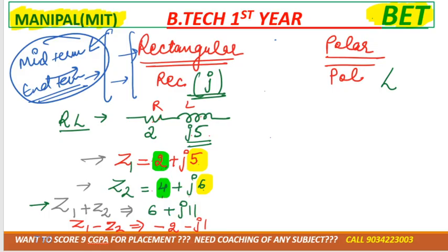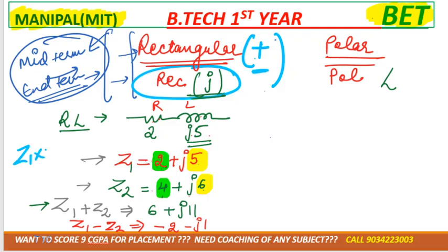Okay, but the thing is that in the rectangular form we can only either add or subtract. If the term is in the rectangular form we can add or subtract, but if we want to multiply these two, if we say Z1 multiplied by Z2 or Z1 divided by Z2, then the term should be in the polar form. So in the polar form we can do multiplication and division, and in the rectangular form we can do addition and subtraction.